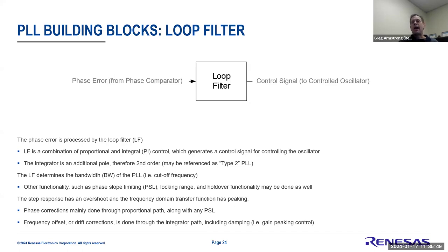But you may want to do averages over a very short period of time, or over a long period of time. From our standpoint, we call that a bandwidth. It's basically saying, how long do I want to wait in my time interval to average out the phase information that's coming in? If I have a very wide bandwidth, like let's say 1 kilohertz, effectively I want a very tiny window. So I may only take about 4 samples, average it out, and immediately spit off an offset. As you can appreciate, that would be a very fast reactor to any changes in phase.